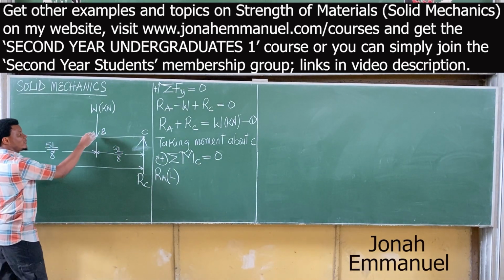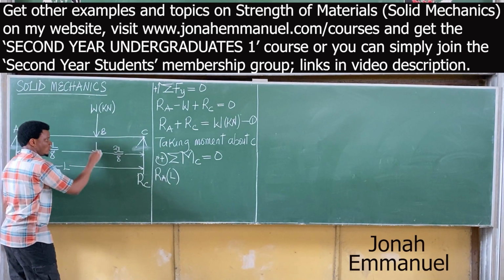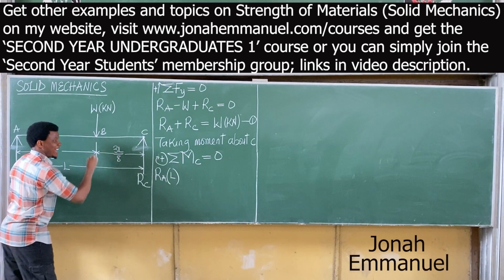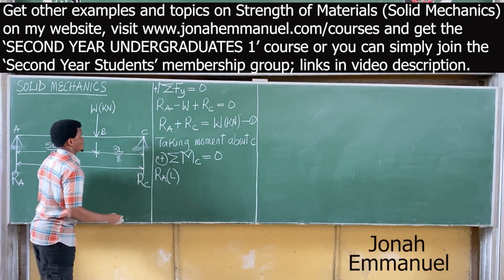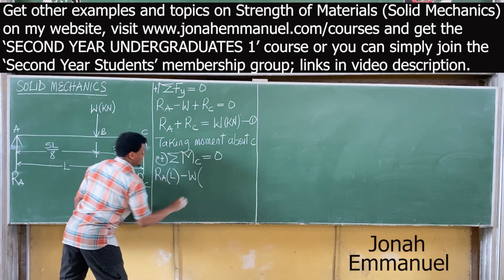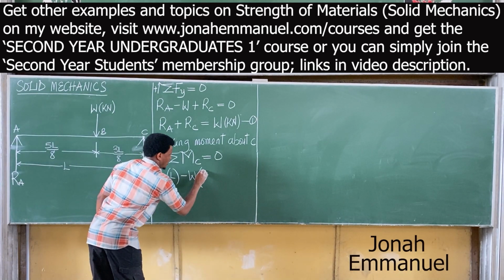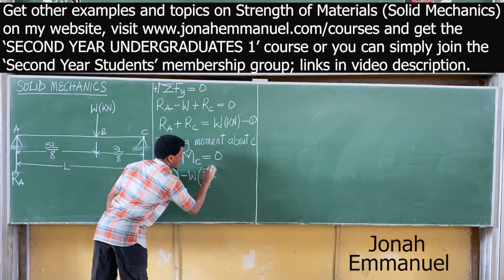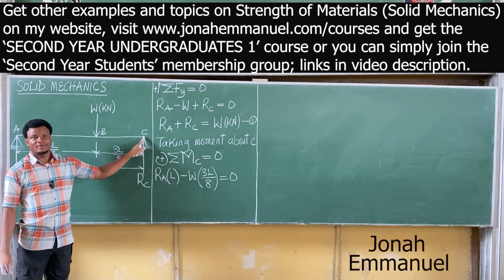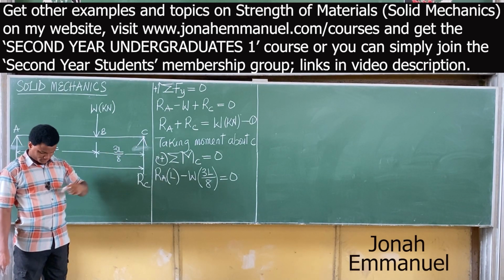Next up, you have W coming down. Trace the direction towards C. It becomes from here downwards towards C like this. So this motion like this is what there? Anti-clockwise. So it becomes what there? Negative. The force there is W times distance from W to C. What's your value? Becomes 3L all over 8. Of course, this man does not matter because it's at that point. So its distance becomes 0.